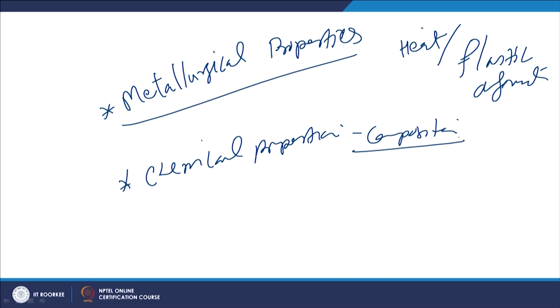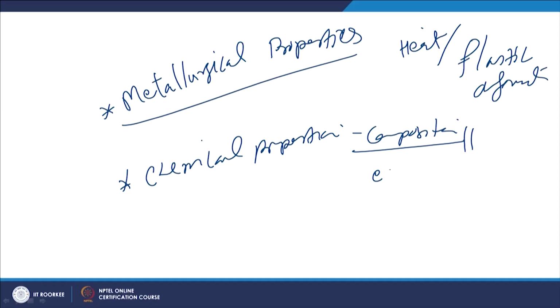Since the composition affects the microstructure and oxidation tendency, the way by which it will react with the surrounding gases at high temperature, it also affects the corrosion behavior, and especially when the metal is subjected to localized heating or controlled plastic deformation during the welding. So, we need to relate the composition of a given metal with the ease of welding. Using those characteristics related to the chemical composition, we will be trying to talk about the effect of the composition on the weldability of the metal.